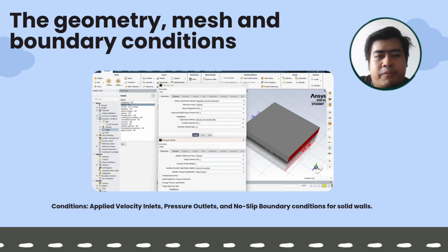Finally, I set up the boundaries and physics in ANSYS Fluent. The fresh air fans are set as velocity inlets based on the ventilation standard. The exhaust vents are pressure outlets, and the walls, pillars, ceiling, floor, and cars are set as no-slip boundary conditions. This completes the setup, making it ready for the simulation.